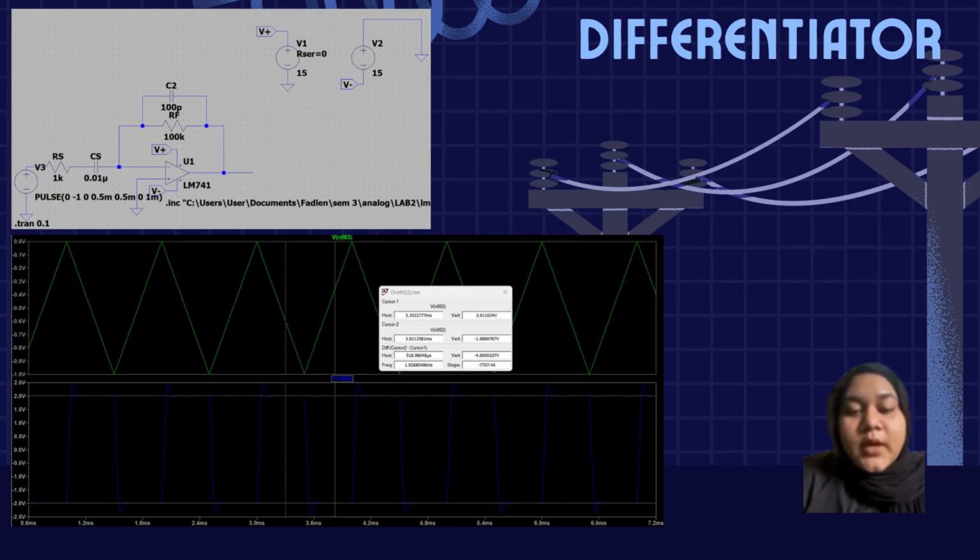Finite op-amp bandwidth and slew rate limited the accuracy of the derivative at rapid input transitions. Input bias current and parasitic capacitance affected the output slightly, causing small deviation from ideal behavior. Adding a 100 picofarad capacitor in parallel with the feedback or input helped filter noise and shape the waveform. The small capacitor improved noise filtering but slightly reduced differentiation accuracy at very high frequencies.